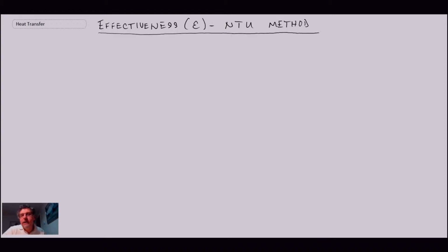If you recall, at the end of the last lecture we looked at a problem using LMTD, where if you do not know one of your exit temperatures and you have no way of solving for it, applying LMTD requires an iteration, which can be a little bit on the tedious side. And so that's why we're going to look at this new method, Effectiveness-NTU.